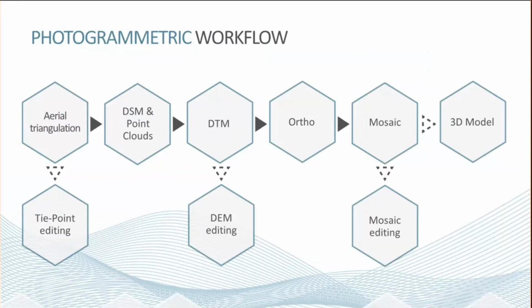Also, just a quick note: we've released a new version of the software this week, and we have added new capabilities to the tie point editing. It's going to be easier to create tie points and to mark them in multiple images. Also, we have modified and added new tools to create GCPs directly from external sources such as LiDAR or reference ortho.